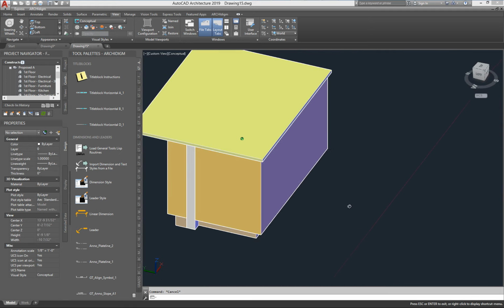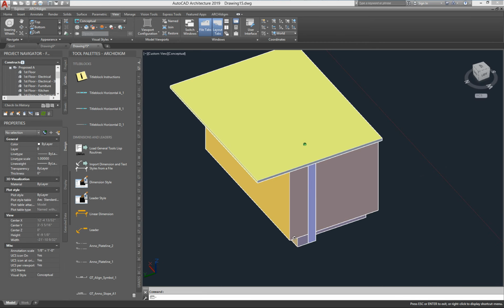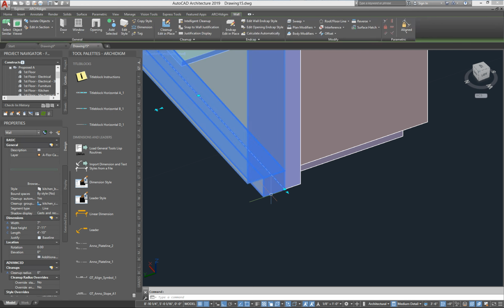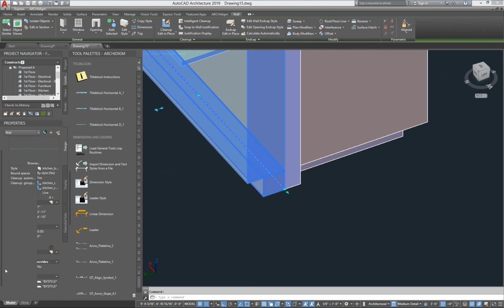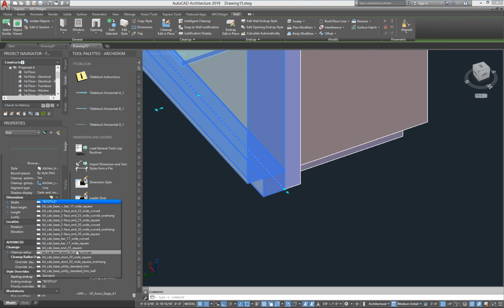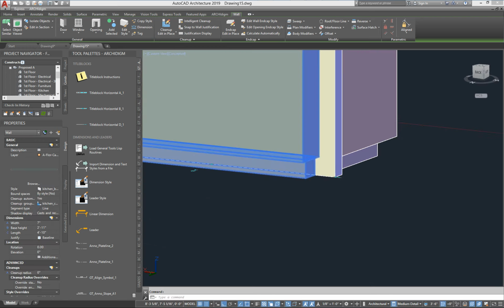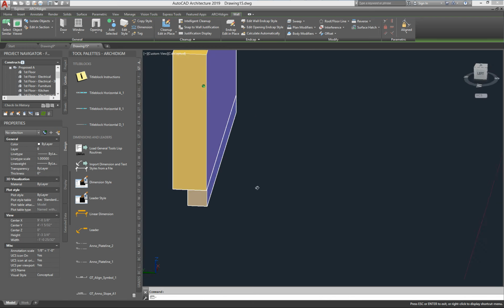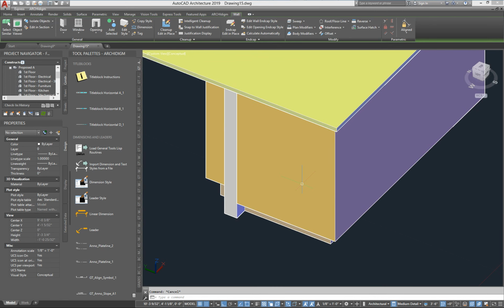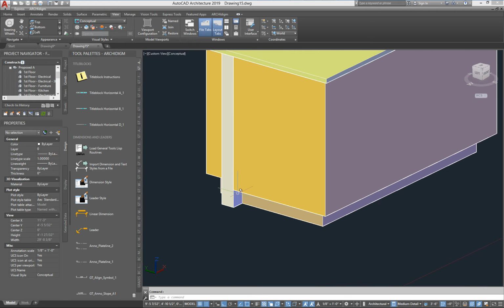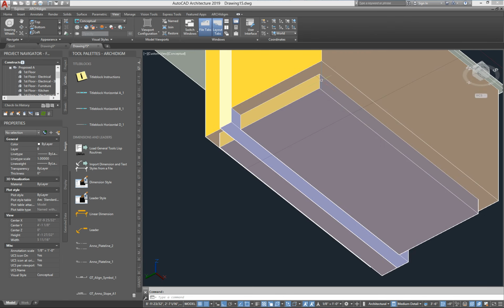And how is all that done? So we might as well discuss that because you're going to need that for this one over here. I don't think you can get away with using the, we'll try here. Try and use the 25 here. Yeah, it didn't like that at all. You can see what happened. See, because it was designed for the cabinet that had a countertop backsplash and was 25 inches deep. Now it's working on the body because the body dimensions are the same. This is 24 with a 3-inch kick at the front.